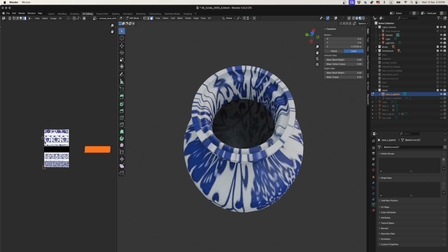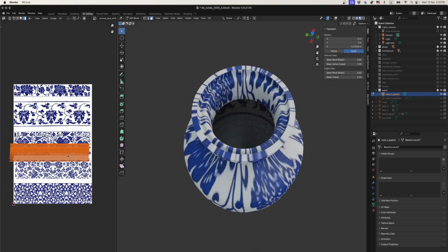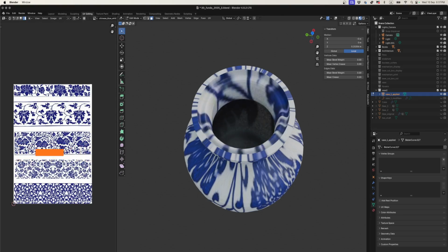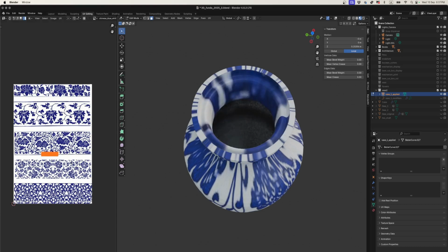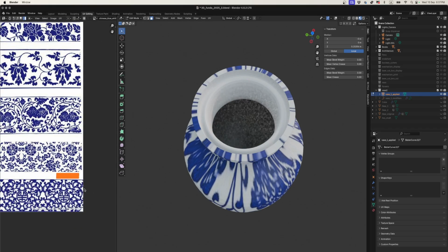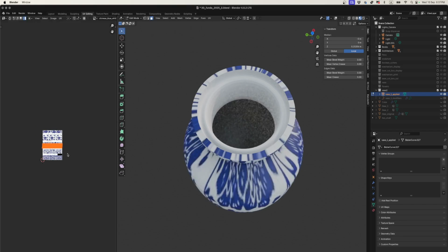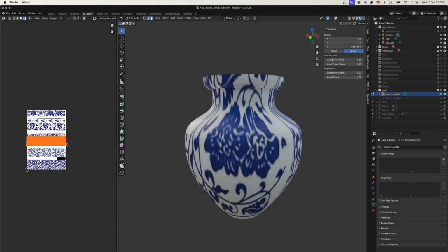Okay, so this looks like this is our inside. That's all right. That's actually good that they're separate there, because what I'm going to do is a bit of a lazy trick. I'm just going to put our inside UVs here, because we don't decorate the inside, right? Inside's going to be white. It's these ones that I want to have properly mapped to my object.